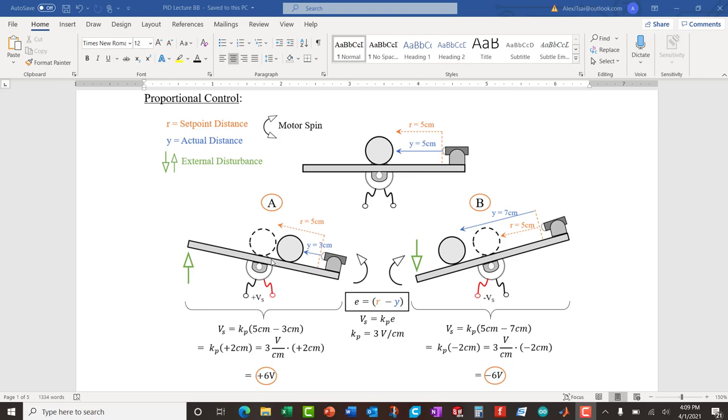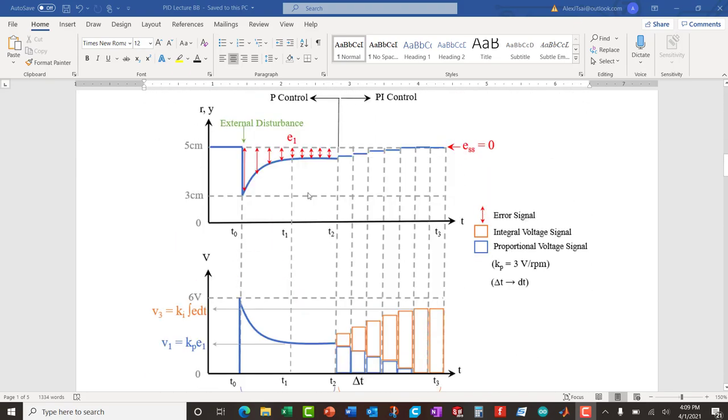Okay, if you do not know how to select the integral control, you can also destabilize the system because of these so-called double poles. Okay, and those who have taken controls may bring memories back of what happens in the S plane. Okay, it's a plane that tells you the location of these poles, these time constants, and the closer you are to the imaginary axis, the closer you are to instability.